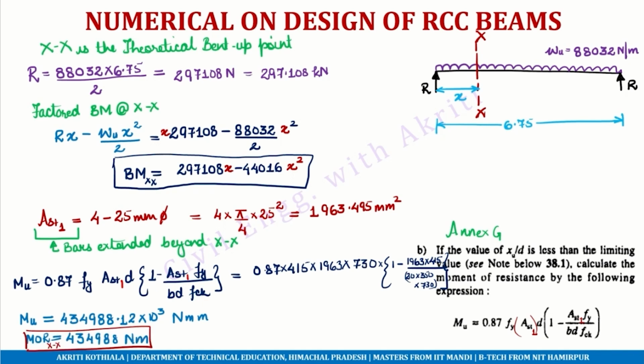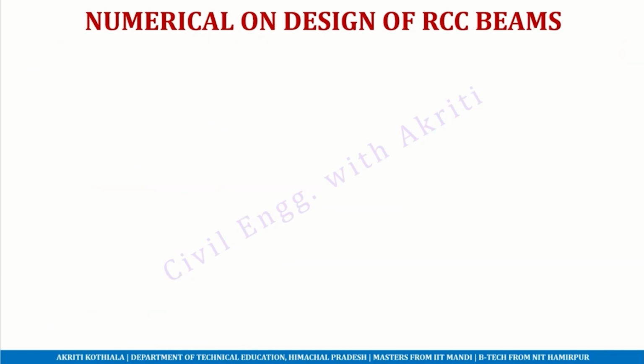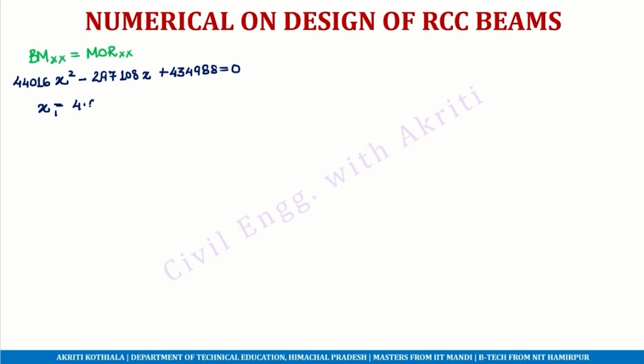Now this moment of resistance should be equal to the bending moment acting at point xx, because this moment of resistance is also at point xx. We can equate these values and obtain a quadratic equation, and this quadratic equation can be solved for x, and we obtain the value of x1 equal to 4.6022 and x2 equal to 2.1477 meters.